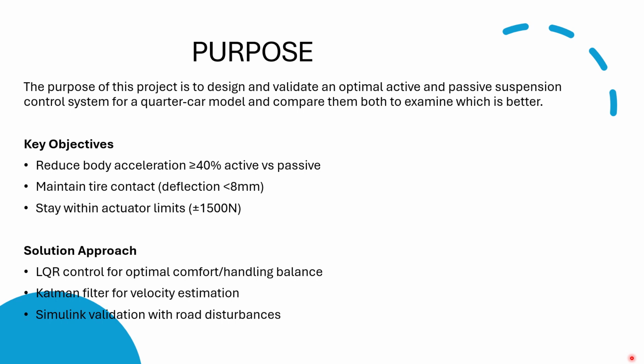To achieve this, we applied LQR control to balance effort, comfort, and handling. And we used a Kalman filter to estimate unmeasured velocities, and we use Simulink to validate the simulation with road disturbances.